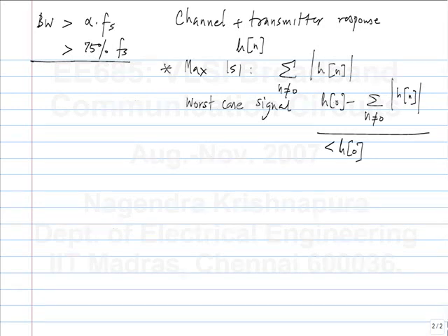And if you add any, let's say, Gaussian noise to it, the bit error rate will be much greater in this case than in this case, when you didn't have any intersymbol interference. The other point to note is h[0] itself is smaller than 1, right? As we saw, as the bandwidth of the channel decreases, again this turns out to be true in general.